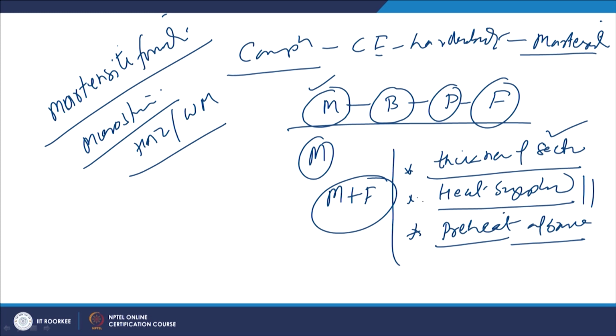In addition to heat input and preheating, if martensite has been formed and you still want to control the undesirable effects associated with hydrogen induced cracking, then sometimes post weld heat treatment is also carried out, so that the martensite can be tempered, and the hydrogen which has been trapped can be eliminated or reduced in the weld metal as well as the heat affected zone.